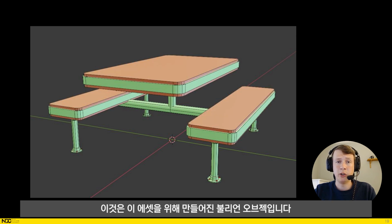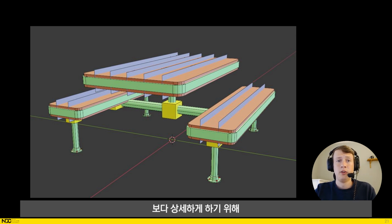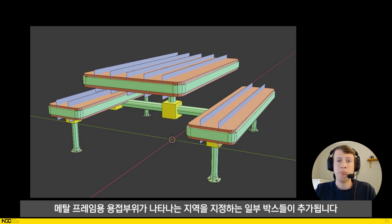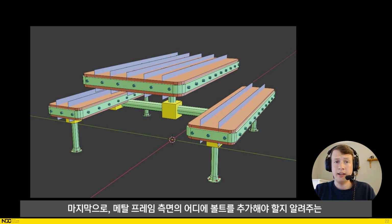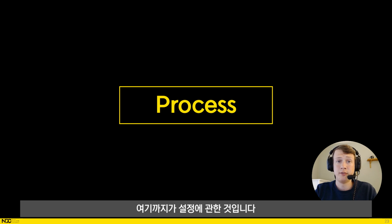Here are the Boolean objects created for this asset. A few small subtraction cylinders for the holes in the feet, and the larger intersection volumes for where the wood is supposed to be. And then some planes are added that are used for slicing the wood into separate planks. For additional details, some boxes are added that designate the areas where welds for the metal frame will appear. And finally, a bunch of cylinders that will tell the process where to add bolts to the sides of the metal frame. That's it for the setup.